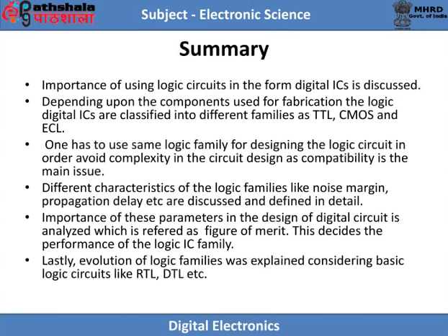One has to consider the logic circuits as a number of basic components fabricated on the single chip. Depending upon the components used in the fabrication, the logic digital ICs are classified into a number of families like TTL, CMOS, ECL, etc. One has to use the same logic family for designing different logic circuits in order to avoid complexity in the circuit design, and compatibility is the main issue.